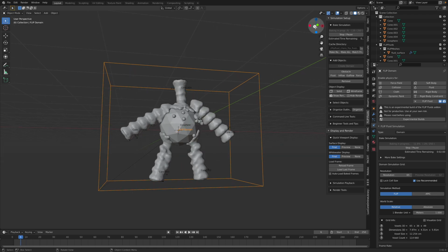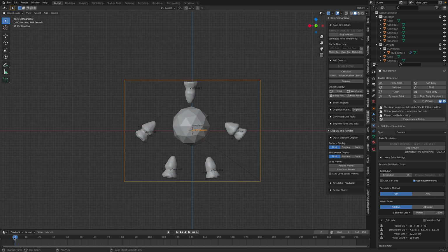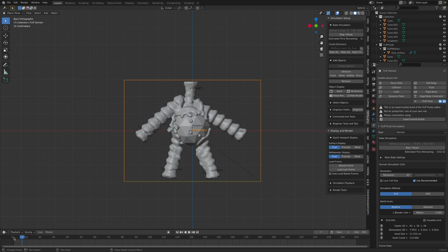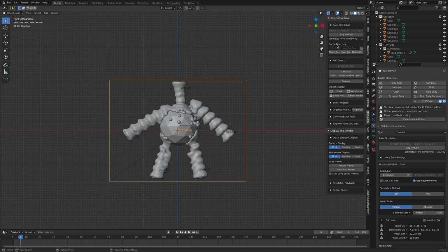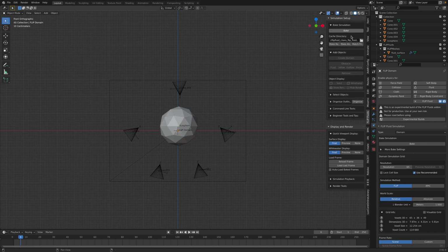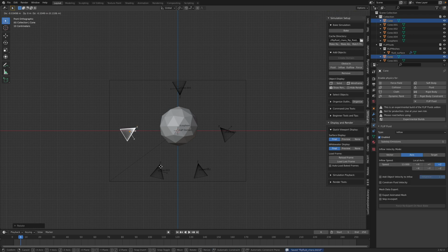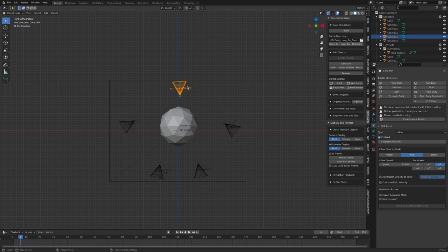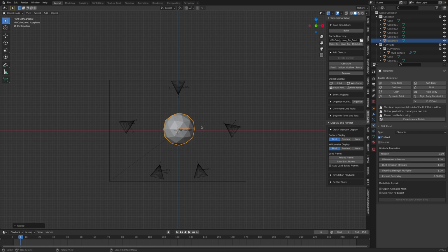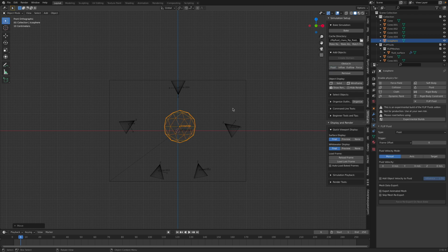It's a bit of a crazy idea, but I think this is kind of fun. You can make a random looking character very quickly. So let's stop this. Stop. Reset. It's more like free-form character creation using fluid. So the top bit, this icosphere can just become fluid. Turn this into fluid, so it's no longer an obstacle. And bake.